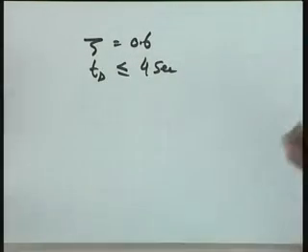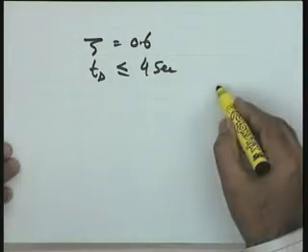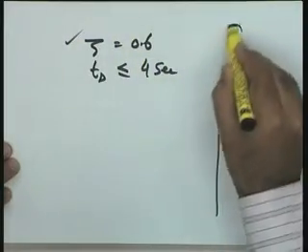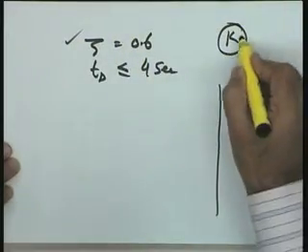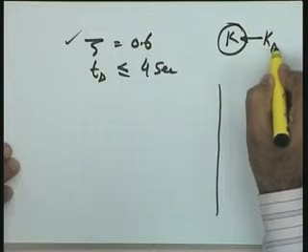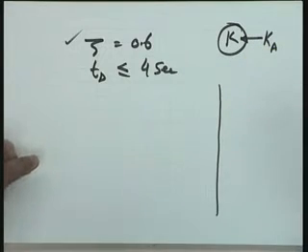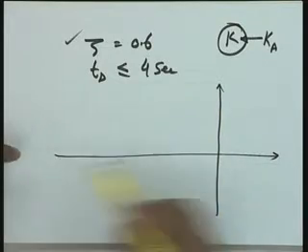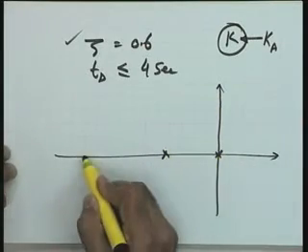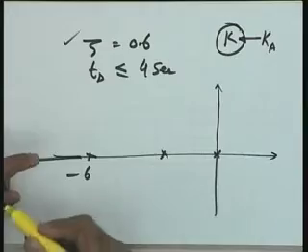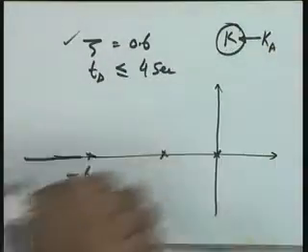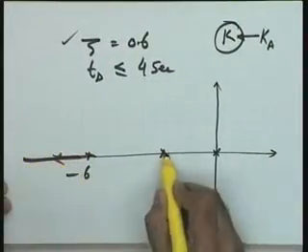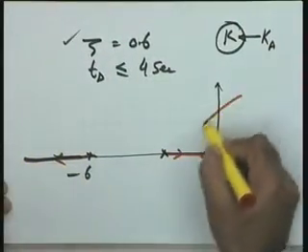Now in the process I am giving you the procedures also. I have only K, the root locus gain, in my control, and by K I mean indirectly I am controlling K through Ka, because K is equal to 60 into Ka. Let me go back to the root locus plot I had made with K as a variable parameter. Minus 6, here, this is the root locus.